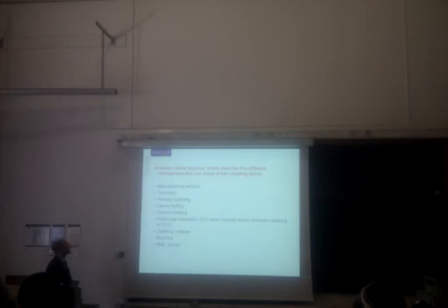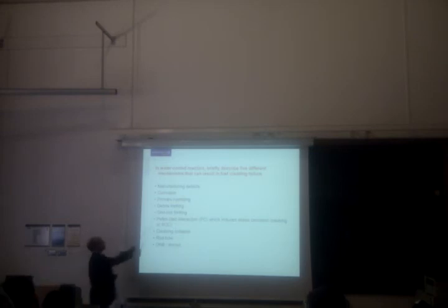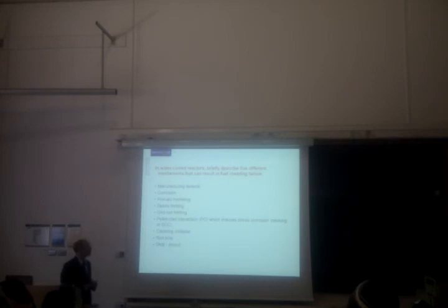The metal will become saturated, and little flakes of zirconium hydride are precipitated out, a little bit like cornflakes under the microscope. They destroy the crystal structure of the metal, and they act as cracking sites. So primary hydriding is something that we get when eventually we have too much hydrogen in the metal, and it precipitates out as flakes of zirconium hydride.